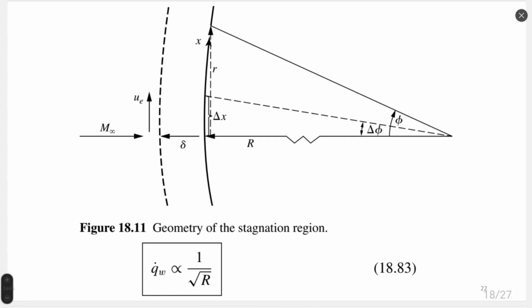This is the answer why small objects cannot re-enter from space and they will burn, because heat flux on small body would be increasing accordingly to decrease of size of the body. This is why only big re-entry capsule can be returned from space. As a nice practical result from application of boundary layer theory to compressible flow.